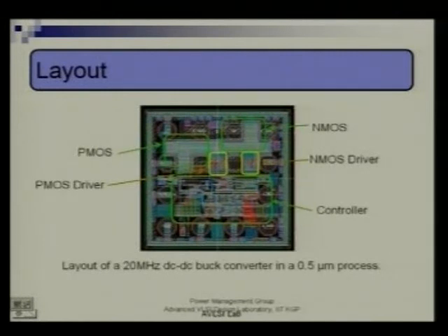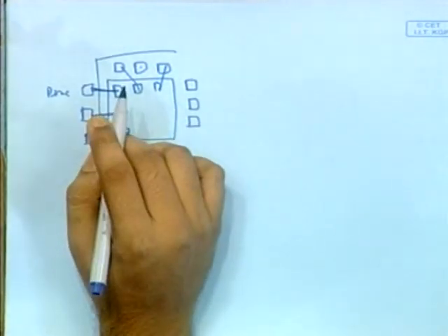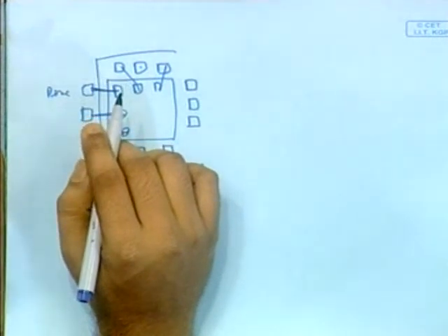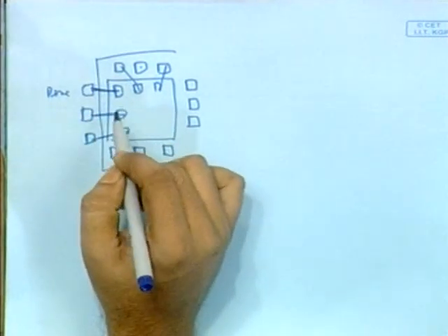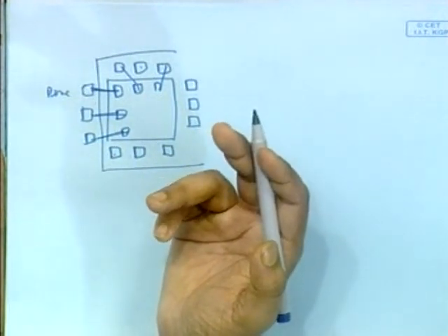Hence the parasitic inductances and capacitances due to these bond wires are eliminated. When we say parasitics, in the 20 megahertz region where this IC operates, these bond wires contribute around 2 nanohenry, and these pads will contribute a few picofarads of capacitance. These might seem very small, but they are significant, and they will cause a lot of disturbance.